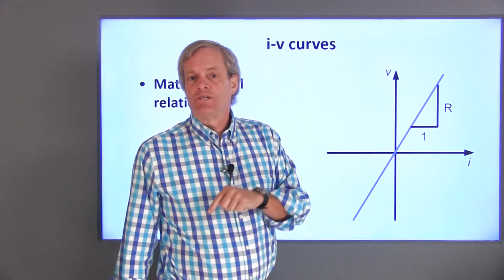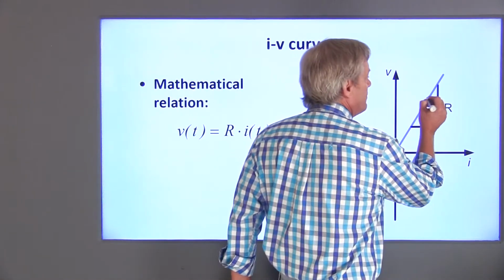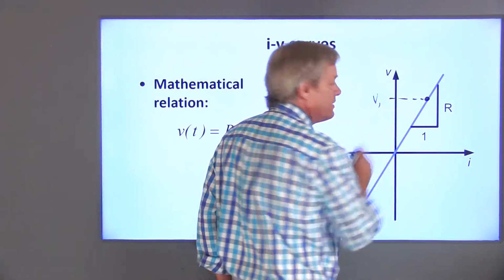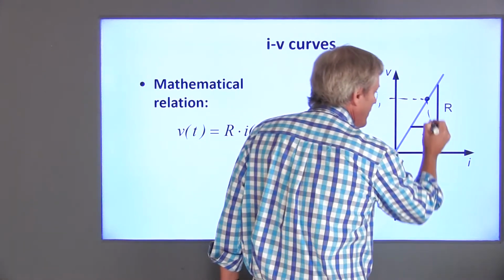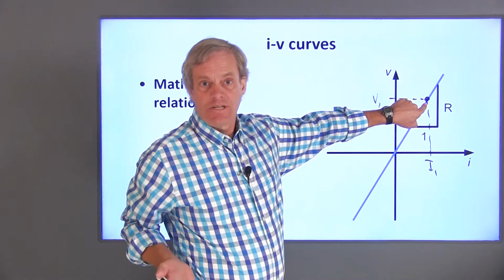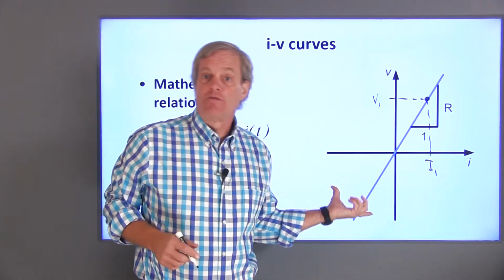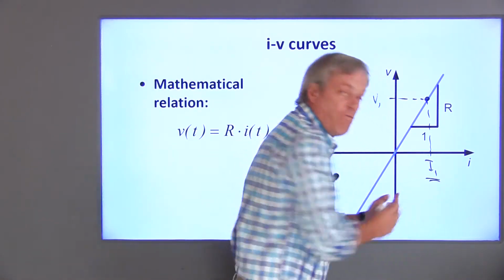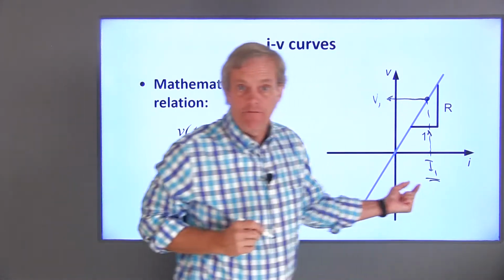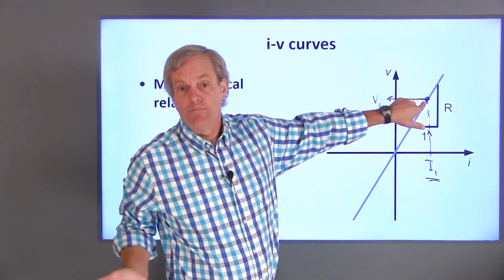Notice that when we measured the voltage and the current for our resistor in the previous demo, we were just measuring one point on this curve. So if we apply a voltage V1 and measure a current I1, we're getting a point on this curve, and the resistance is just V1 over I1. Alternately, if we're given this curve and we know, for example, how much current we want, we can read the necessary voltage directly from this graph. This desired voltage-current relationship is sometimes called the operating point.